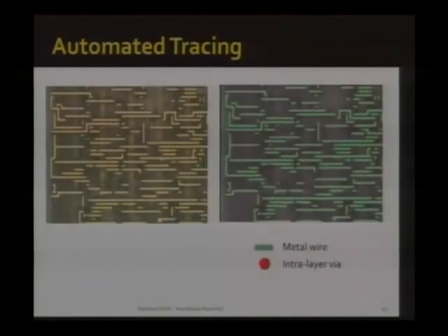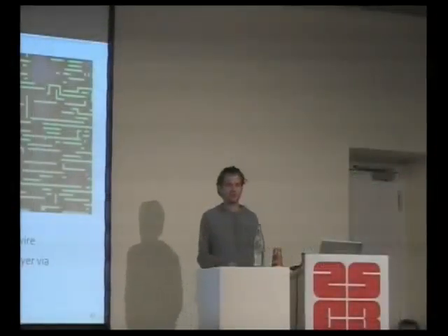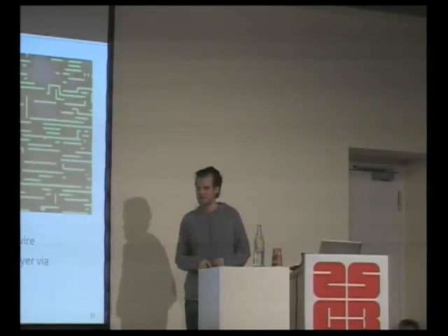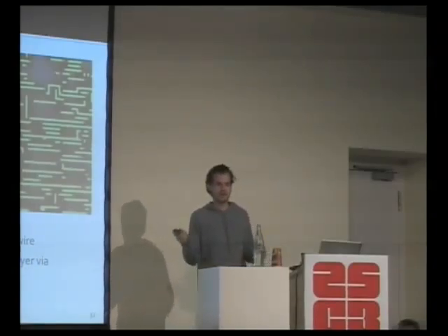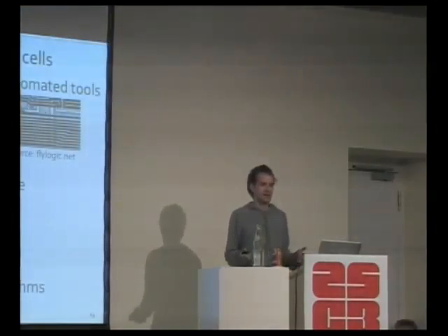So we have a map of where everything is on the chip, and we know what is connected to what, which gives us a circuit plan, right? And the circuit plan is basically equivalent to source code. It's very messy source code because it wasn't ever meant to be read back, but it's nice enough for us to understand the functionality behind it. Is that clear so far? That we can find the circuit just from a polishing setup, a simple microscope, and a few open source programs?